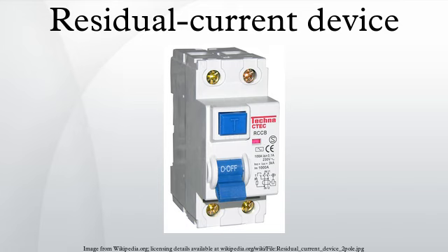However, Rubin began working on a completely novel system with greatly improved sensitivity, and by early 1956, he had produced a prototype second harmonic magnetic amplifier type core balance system. The prototype MAGAMP was rated at 220 V, 60 A and had an internally adjustable tripping sensitivity of 12.5 to 17.5 milliamperes. Very rapid tripping times were achieved through a novel design, and this combined with the high sensitivity was well within the safe current-time envelope for ventricular fibrillation determined by Charles Dalziel of the University of California, Berkeley, USA, who had estimated electrical shock hazards in humans.